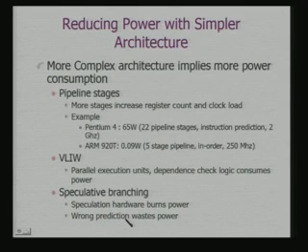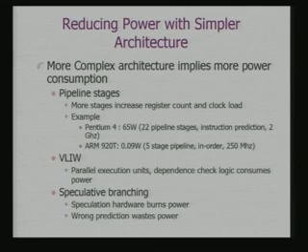In fact, this is pretty complex hardware. If you go back to the Pentium example, it uses instruction prediction. It predicts which instruction is to be executed in future, and on that basis it tries to prefetch and keep the pipeline full. That prediction process consumes substantial power.